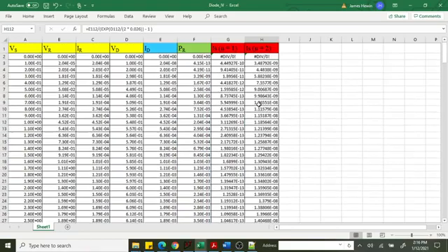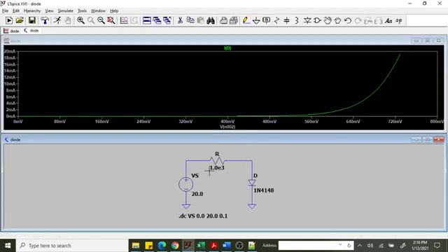Anyway, that is just some things I wanted to present. Basically, how in LTspice you can do a DC sweep, sweep the voltage, and observe the characteristics of the diode. The voltage across the diode is going to increase to close to around 0.7, and the current will increase as well as we increase the source voltage.